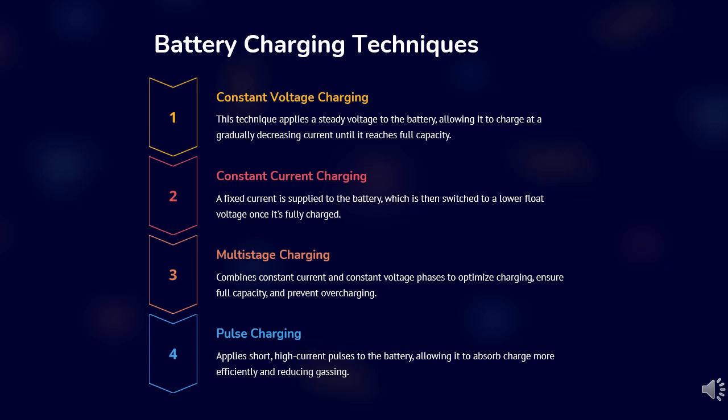This enables the chemical reaction to keep pace with the rate of inputting electrical energy. It is also claimed that this method can reduce unwanted chemical reactions at the electrode surface, such as gas formation, crystal growth, and passivation if required. It is also possible to sample the open circuit voltage of the battery during the rest period.